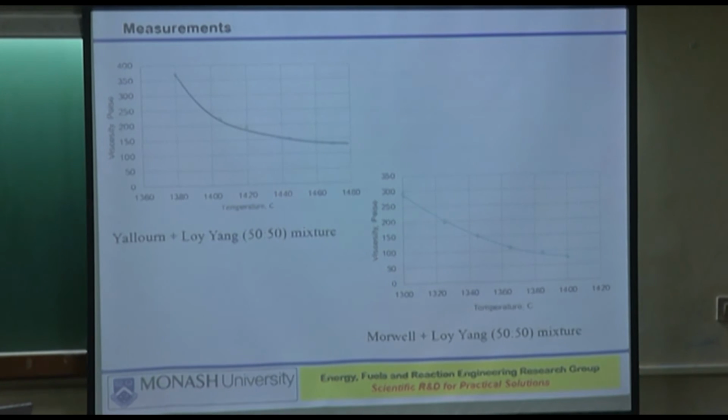And those which fall down are collected in the bottom ash hopper in water. And then periodically those are discharged away. So that's a normal part and a very manageable, established part of plant operation, boiler operation. There's manageable risk in it.